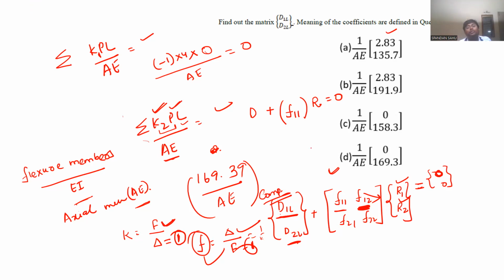I think that will be encountered in the slope deflection method. It can be incorporated here also, but it will be too long. I haven't taken it because even for this much question it took 3 hours. I have not seen support settlement for the force method, only in slope deflection. In the next class, I will take an example with the three moments theorem. Here support settlement might not be there, but lack of fit can be there in a truss.